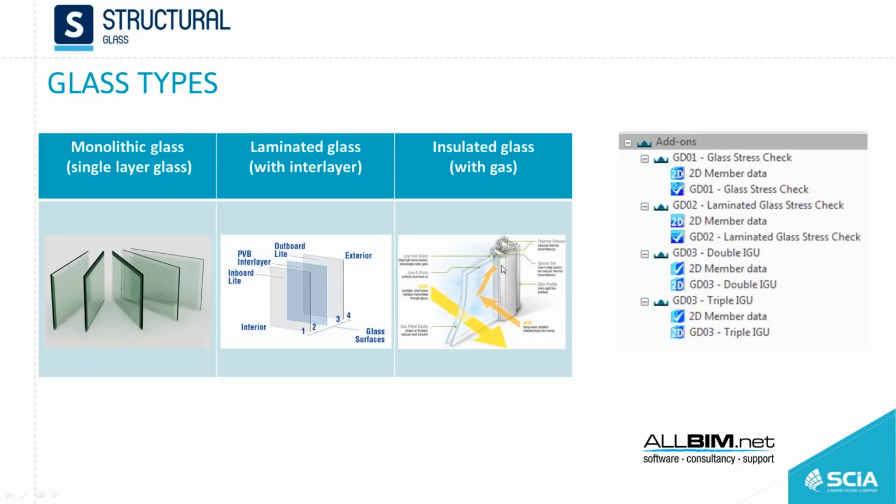The gas inside is subjected to temperature variation, and this will lead to a volume increase or decrease. So this volume transformation will be translated in an isochore pressure. So this isochore pressure will act in different directions in winter against summer, and it will actually manifest as an extra pressure on the glass panes.